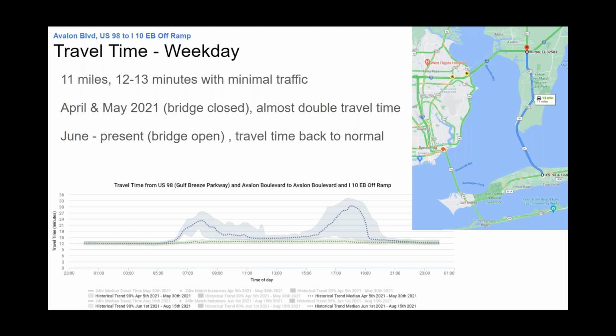And this is where you're really getting into demand management of vehicles. You can see that there's a spike in the morning and a spike in the evening. If the public was aware of this extreme travel time and this change in patterns, then it can start to be normalized. So instead of everyone coming at 7, maybe they can start coming at noon, when it's more normal, instead of all trying to get through the same corridor that just wasn't built for that throughput. That's something that could be taken away from this, as well as a backup plan that maybe needs to be built and expanded on in case this happens again. But at the same time, you can almost manage the demand and start normalizing it.